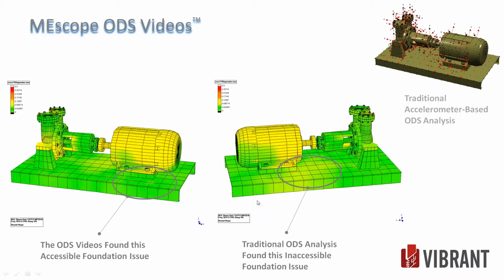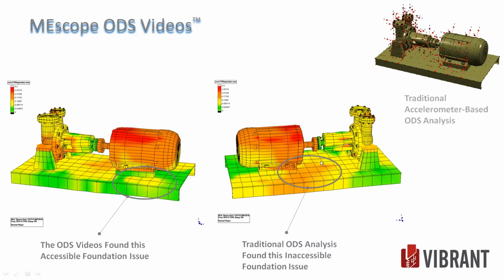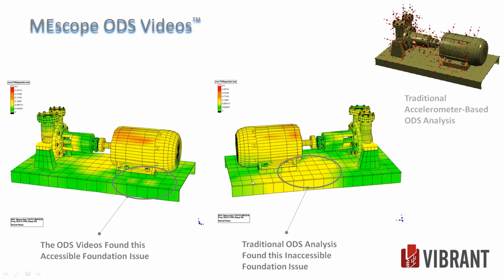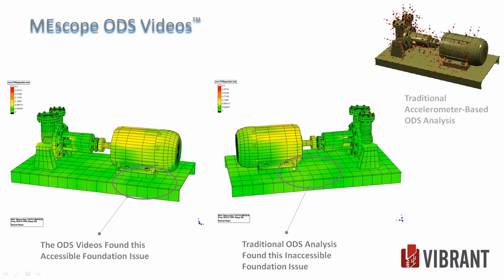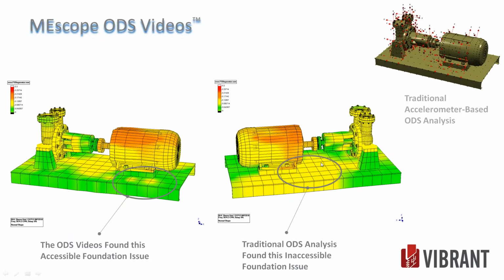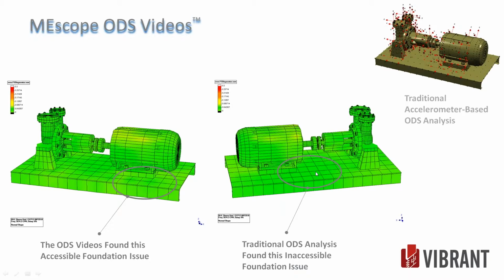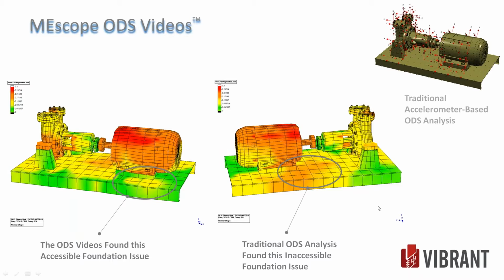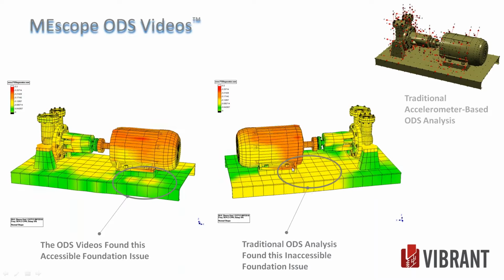This is the side of the unit that I couldn't see. So I could take vibration measurements all the way through here on the other side. There's a much bigger delamination problem on this side. Okay, we didn't detect any cracks in the welds or anything like that. It's just that the grout is coming free from the deck plate under here for some reason. Okay, so it turns out we had to do a little more investigation into that, how they wanted to fix it.